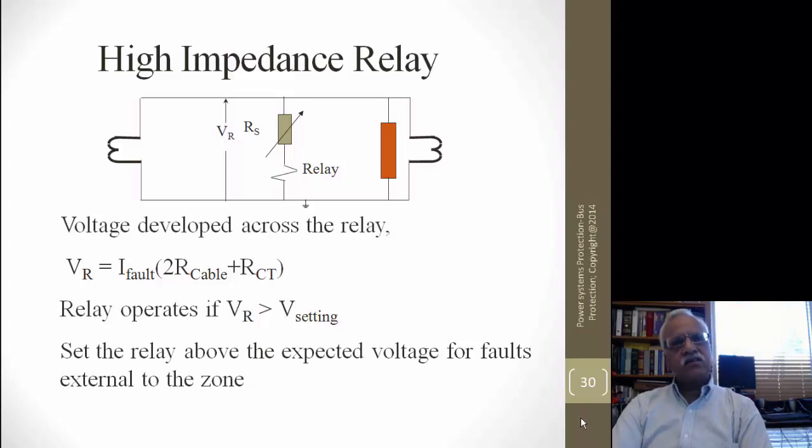And we also talked about the phenomena of CT saturation. We said that the CT will never saturate at time t equals 0, and even if it saturates, it comes out of saturation after a certain amount of time. We make use of these two to make a bus protection a very reliable and secure device.